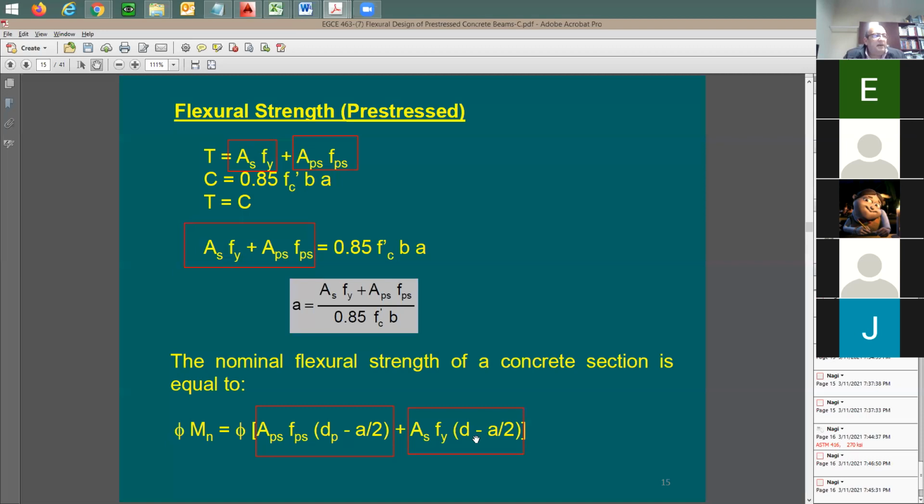So some people would say, let me add enough reinforcing here so that the beam is going to be able to support itself, right? Now the beam is supported on the conventional rebars. And after that, they start to apply the post-tension force. So the beam now is not 100% flat, it's going to be coming down a little bit. Now they apply the post-tension force. Then they cast the concrete topping on the beam, the concrete slab. And after that, they apply the live load. So in some cases, this reinforcement is going to be important for design purposes because you designed it at the beginning so that you're going to be able to take all the shoring and all the formwork out.